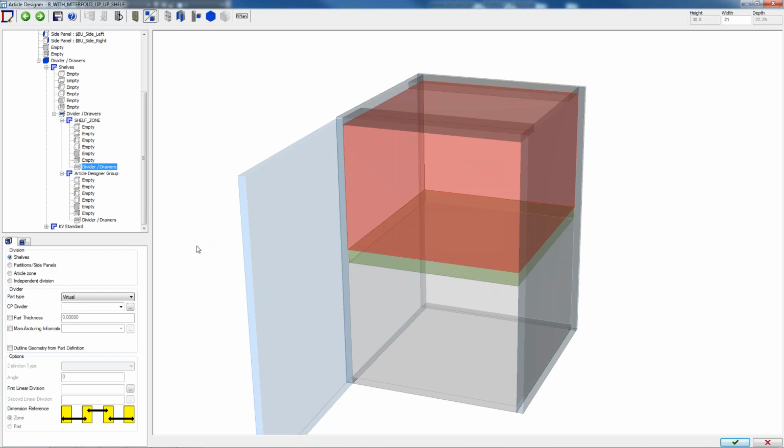Okay, a little help here. Okay, so we want to make the shelf, divider drawers. Go to your shelf, do construction principle, lift the part. Come on, we just did this like twice, three times. If it's not clicking for you, let's take some notes. Divider drawers, the shelf. We're making a shelf, right? Right. Wrong, divider drawers. You already have the shelf assigned on the divider drawers above that. Yeah, right there. We're going to make a lift down miter for it.